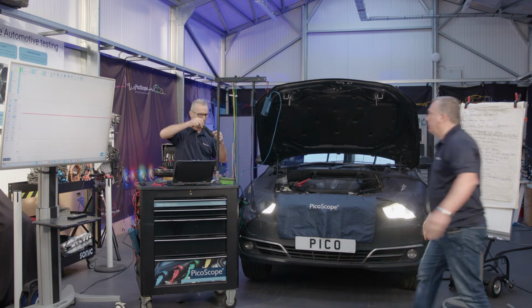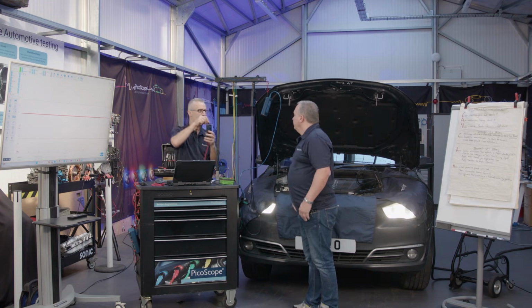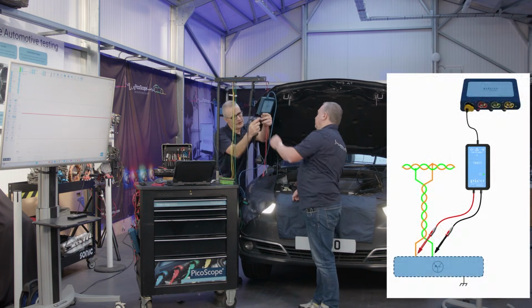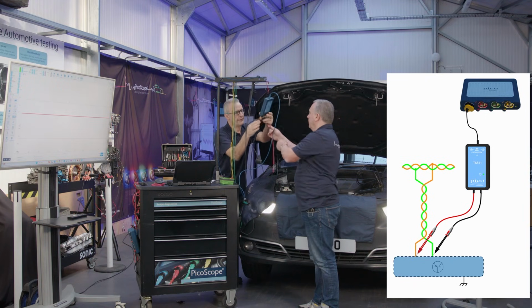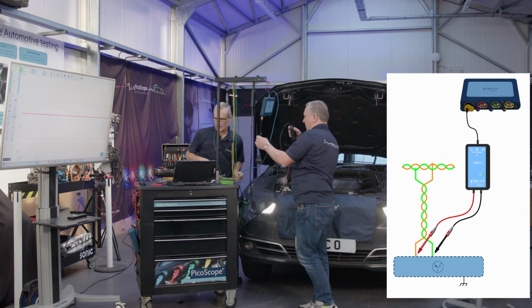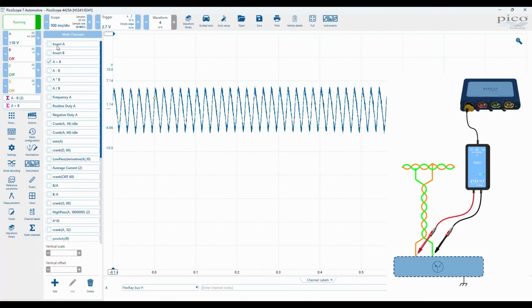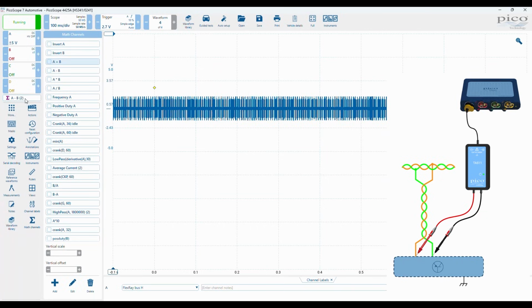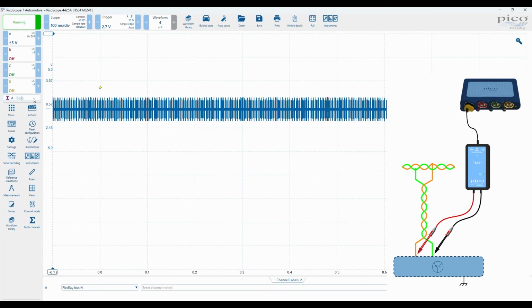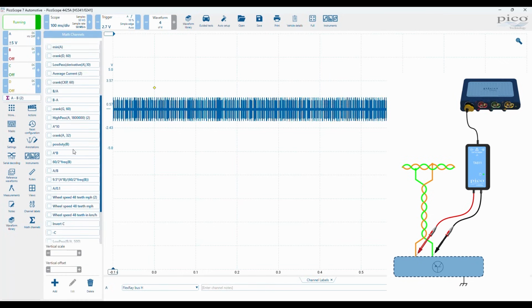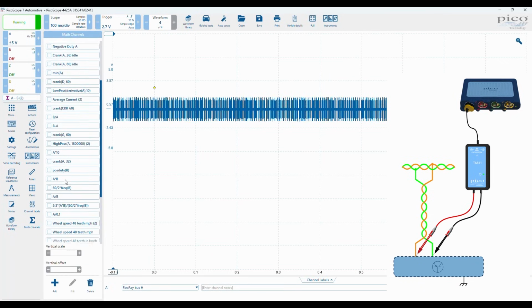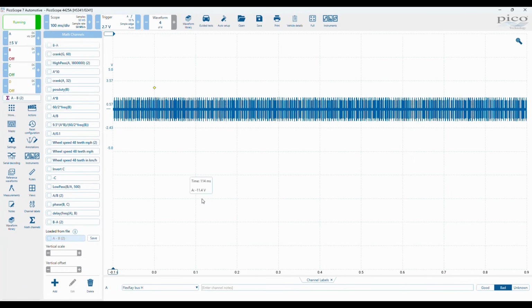So here we have our differential probe. This is high impedance. So using a single channel now, we can connect directly across bus plus and bus minus. We'll take away math channels because they're not required anymore. We're just going to do a FlexRay capture.